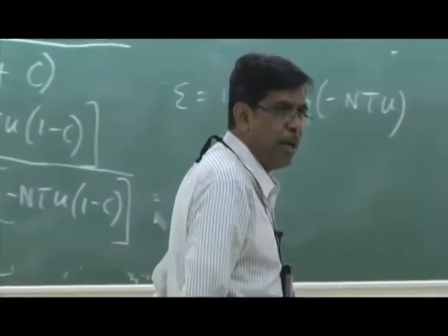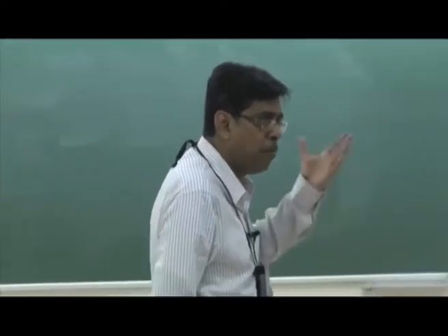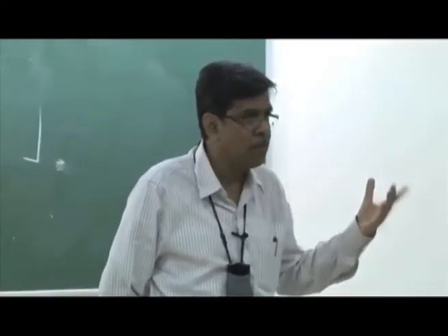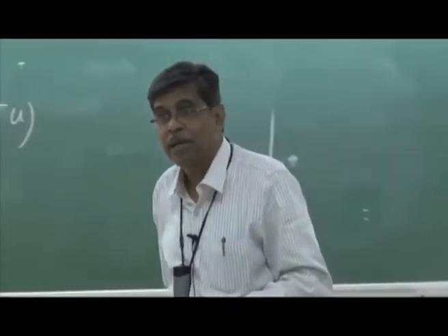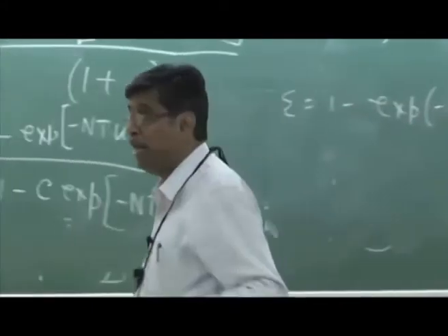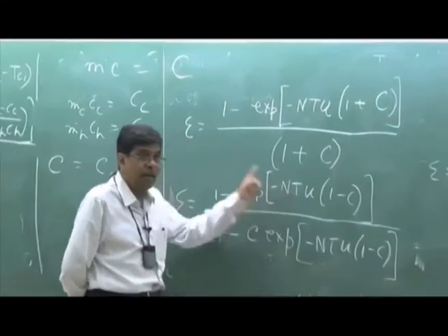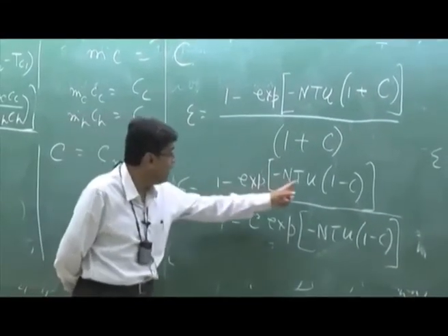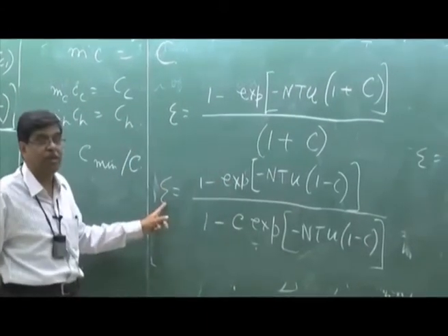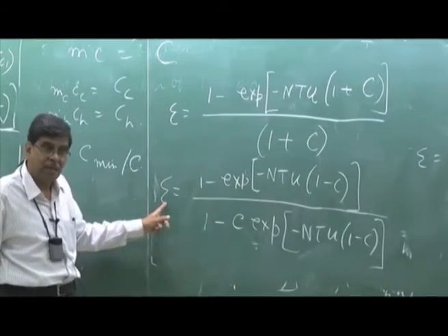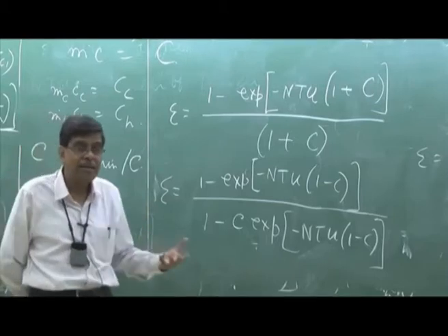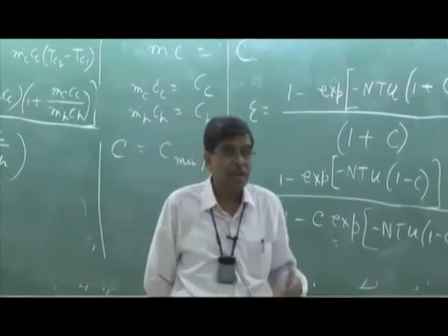To find out effectiveness, quickly temperatures are found. But where the temperatures are given, sizing is to be made, LMTD is useful, because knowing epsilon, NTU as a function of epsilon will be a little difficult. You understand? This may require tedious calculations or iterations.